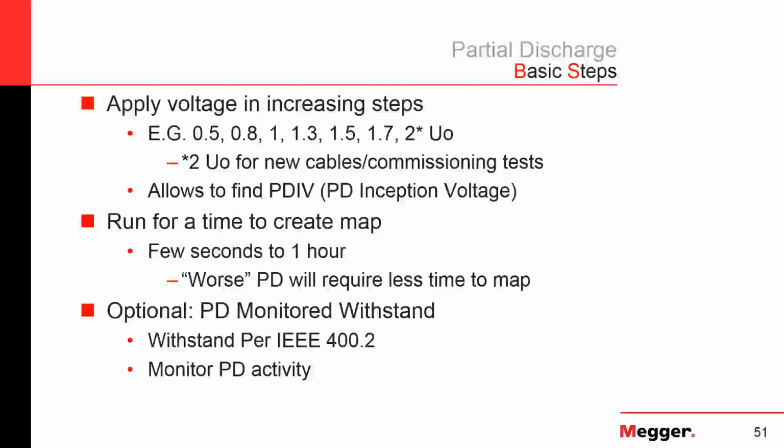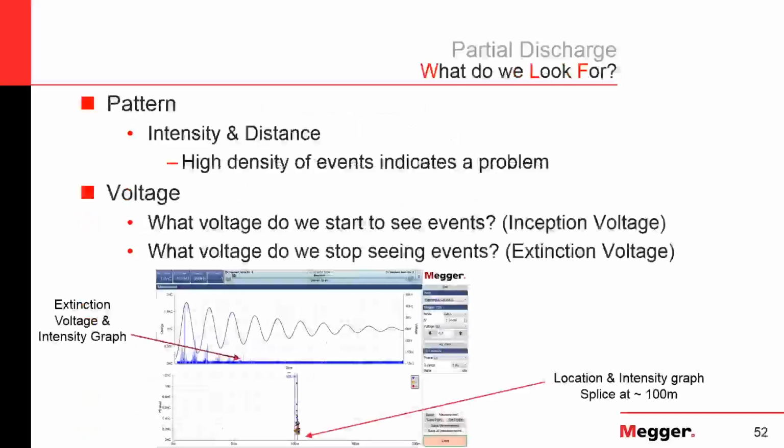And that may be extending the VLF withstand test more to cause that point to fail, or doing some more partial discharge investigation.